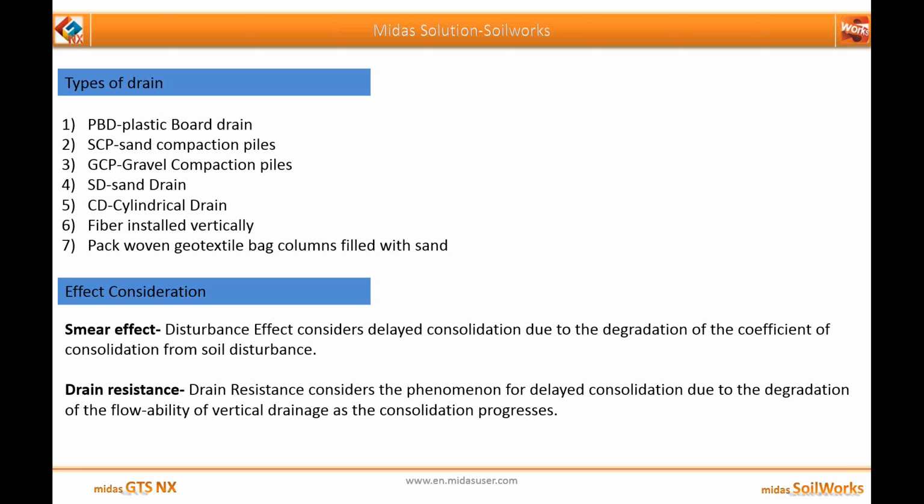Disturbance effect considers delayed consolidation due to the degradation of the coefficient of consolidation from soil disturbance. Now, drain resistance considers the phenomena for delayed consolidation due to the degradation of the flow ability of the vertical drainage as the consolidation progresses. So, both the kind of effect could be considered while considering such type of drains.